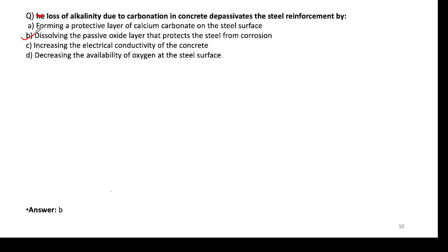because now there is a layer formed on the steel surface that will protect against the ingress of chloride ions or many other elements which can corrode the steel beneath it. Carbonation is also one of the reasons that dissolves that oxide film, due to the lower pH. A lower pH of around 9 can lead to depassivation of the steel. The passive oxide layer will be destroyed because of the lower pH, and can lead to corrosion due to carbonation.